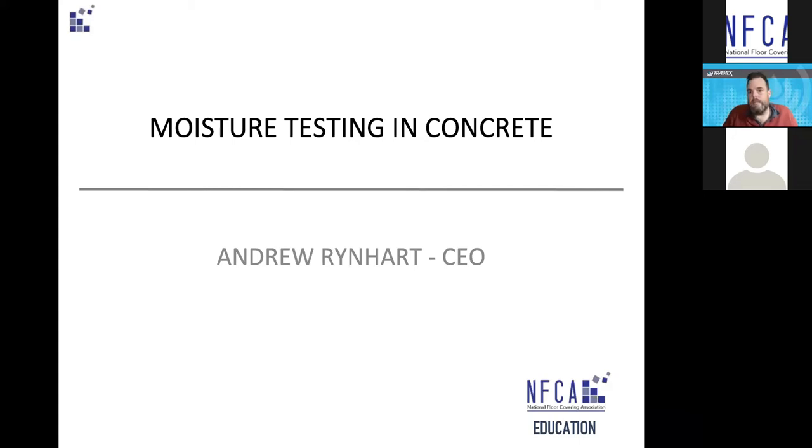And then the carbide meter is a moisture content meter. The calcium chloride test, which is used a lot in the United States, is a measurement of vapor. It's measuring the rate of vapor coming out of the concrete. And you can do gravimetric testing, or even our meters are calibrated based on gravimetric testing, so that gives you an indication of the moisture content. And there are other meters as well that do something like that.